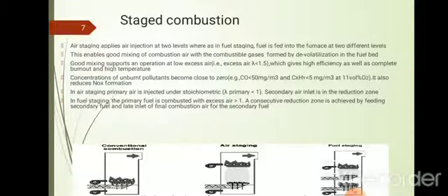And the third figure is fuel staging. The difference is that in fuel staging, fuel is entering in two stages. So that is the difference between fuel staging and air staging. That means we require two grates. In fuel staging you require a two grate system, but in air staging we require only one grate, but we are supplying air as primary air and secondary air. So mostly staging means we are referring to air staging. Fuel staging has very limited application.